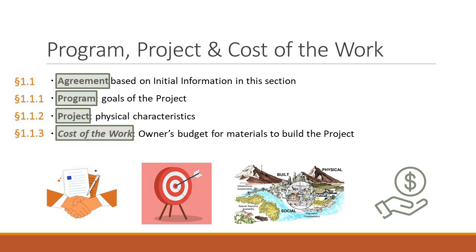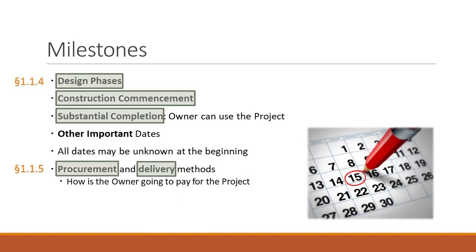If you start designing a house and you design it for $1 million, and it goes out to bid and it comes in at $1 million, and at that point, and only that point, the owner says, well, my budget included paying you your $150,000, so you should have designed me an $850,000 house instead of a $1 million house. Then you understand how you look at it. So it's important to ask when you have a budget discussion with an owner, so they understand the difference legally or contractually. Cost of the work does not include anything other than materials and labor to build the structure. Okay, moving on.